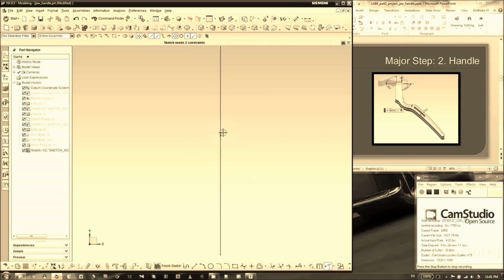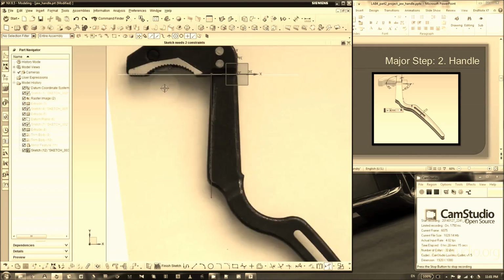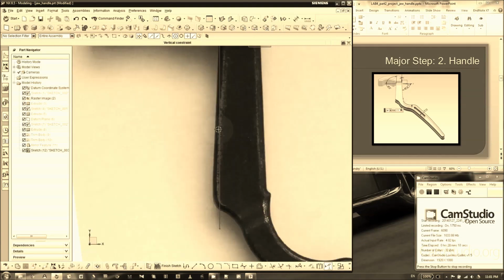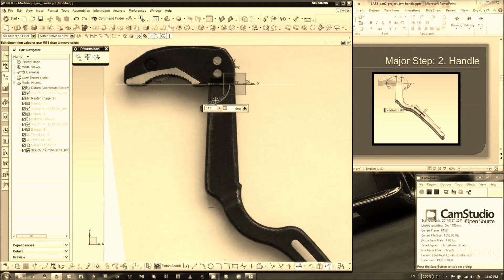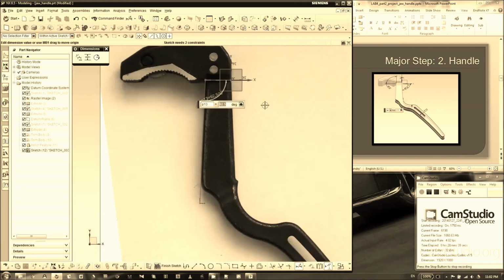If you cannot see, I'll show you this constraint here, which is not what we want. So we're going to hover here, and you can see the vertical constraint. Click, delete this. And if you look closely at the slides, we do have an angle for that, for you to refer. So 92.5 degrees, which matches okay with the image.